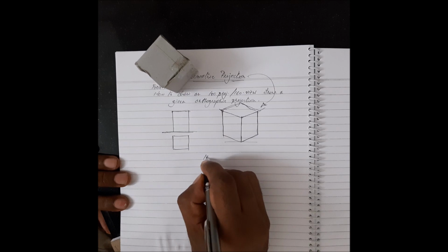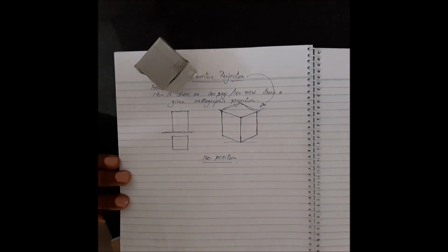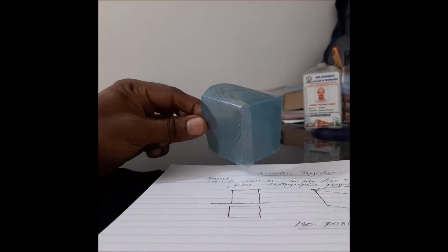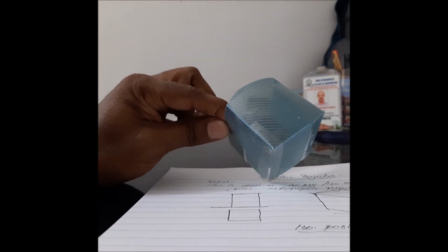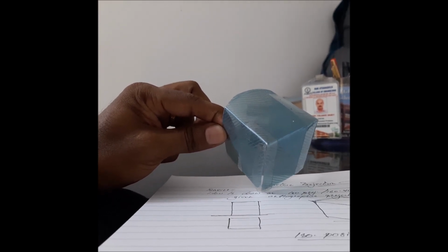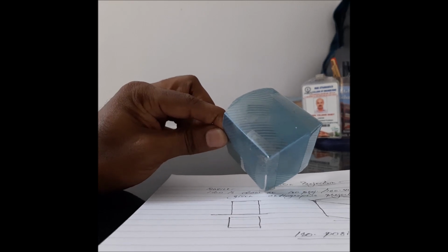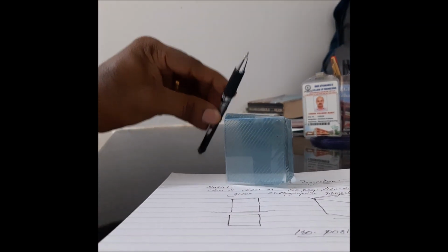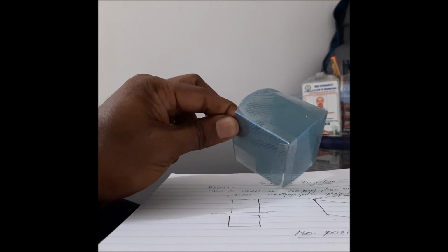So isometric position is actually defined with the help of a cube. Let's say you have a cube like this, and the cube is kept in such a way that the solid diagonal of the cube is perpendicular to VP. We have done this problem in the orthographic projection topic, so I guess you remember it. If you keep a cube resting on one of its face corners, and the solid diagonal of the cube, the diagonal connecting this point and the diagonally opposite bottom corner, perpendicular to VP, this is what you get.